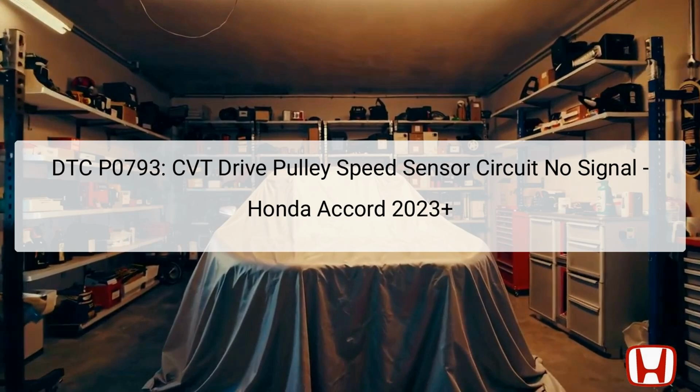The TCM interprets input from this sensor to determine if the transmission is functioning correctly and to adjust its output and strategy accordingly. When the TCM recognizes a failure or communication issue with the sensor, it logs the DTC P0793 to alert technicians that further diagnostics are required.